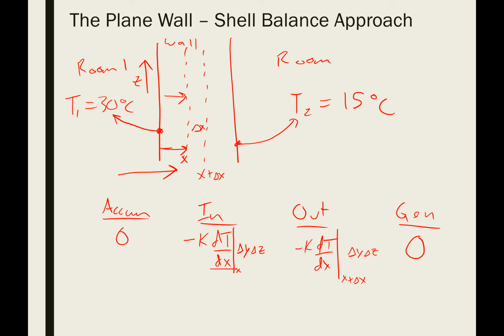You would have made this discrete approximation of the heat equation, but then using software, you could actually get a pretty good approximation of what the temperature profile looks like. That approach doesn't get all that much more complicated when you're dealing with 2 dimensions or 3 dimensions. It just becomes coding and organizational skills that help you to solve that problem. While trying to integrate that second order PDE that varies with time and with 3 dimensions gets extremely ugly and complicated to do analytically, to do that numerically becomes really easy.